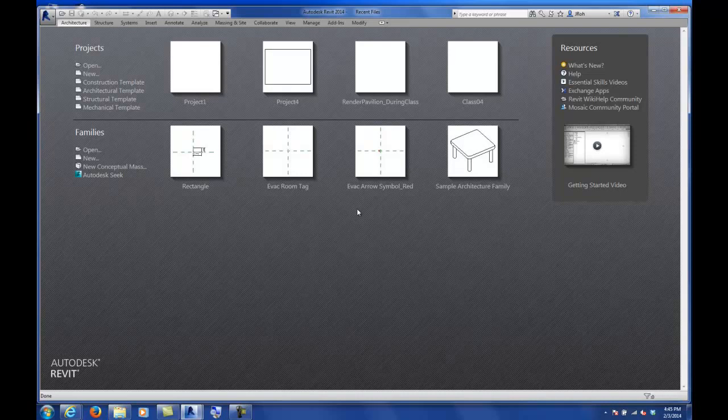Actually, the one part about Revit is we can start at a very schematic level. So if you guys are working with these massing elements, and this is one of the things I talked about at the very beginning, we can mass and push and pull and do these things that represent whatever models you're working in. But we can also tie them to some kind of schedule that we can report any kind of programmatic data. Are you guys working with any kind of program at this point, some kind of square footage? Yeah. So we can make that connection here today, and you guys can start to experiment a little bit with the massing tools. So one way of doing that, I'm going to close out of that file that we're in, and let's go ahead and go into the architectural template.